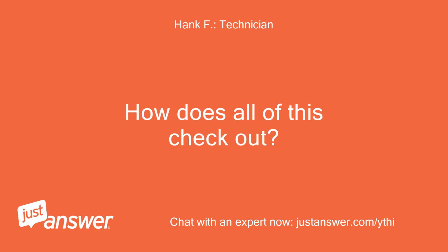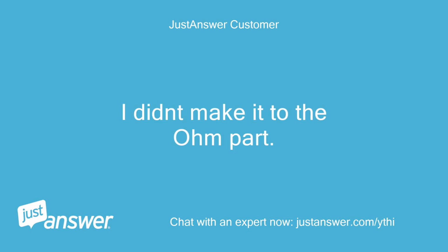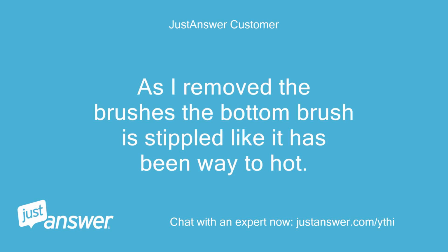How does all of this check out? Okay. I didn't make it to the ohm part. As I remove the brushes, the bottom brush is stippled like it has been way too hot.